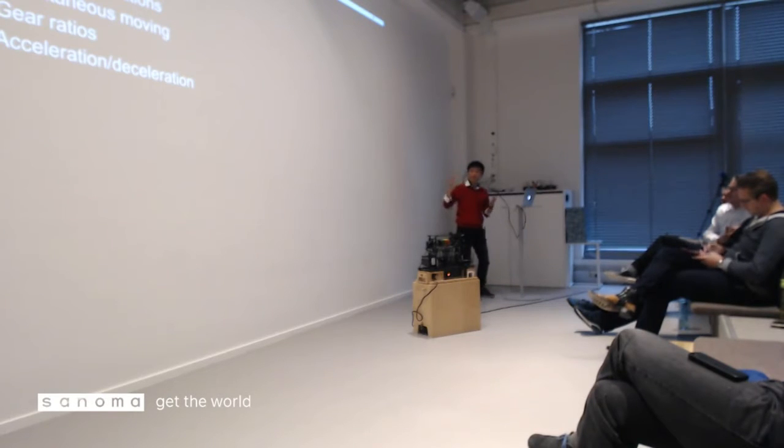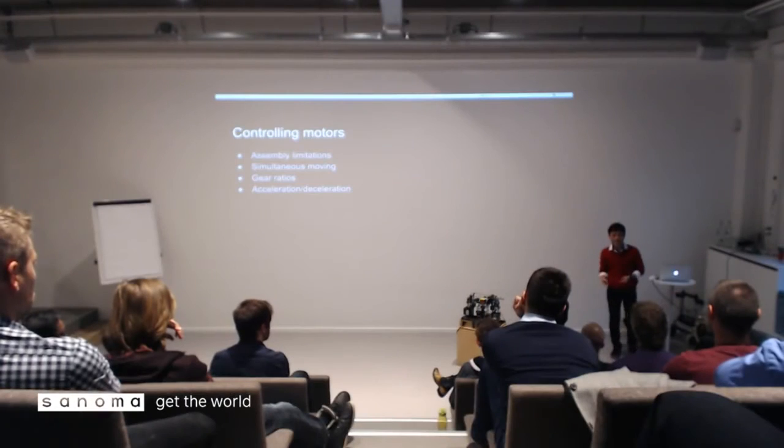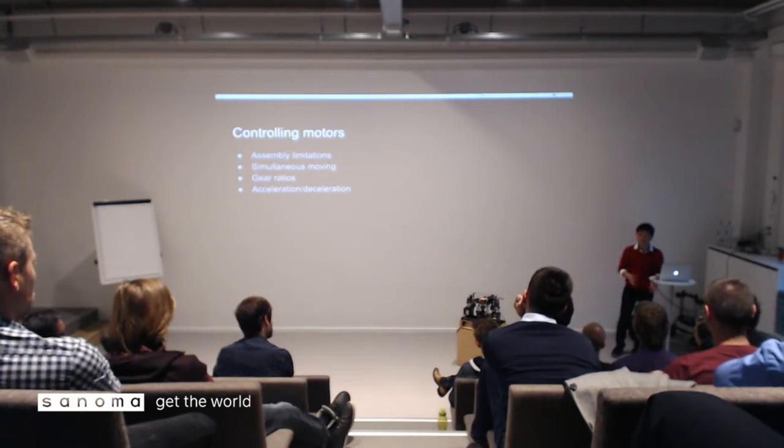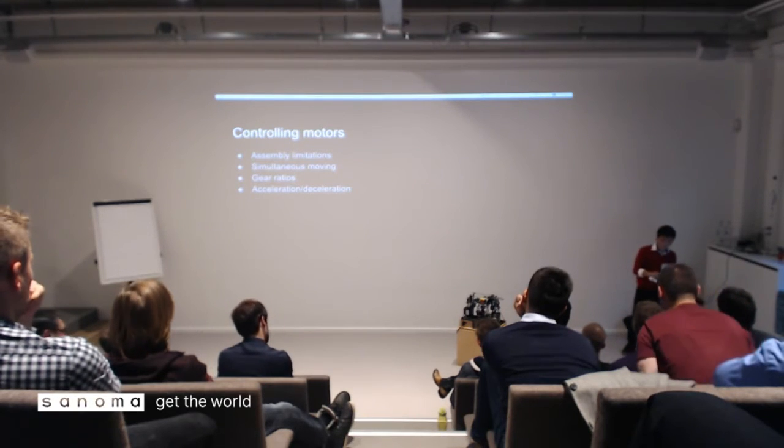Probably the most interesting part is the acceleration and deceleration, because if you're working with motors, if you want to achieve higher speeds, because of the inertia, you cannot just start rotating it at high speed right away. So you have to start slowly and then accelerate and in the end decelerate. It's not very obvious from the beginning, but it's essential in the end.